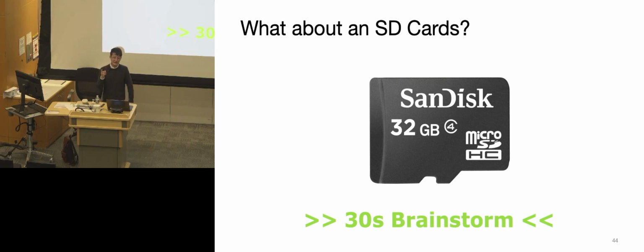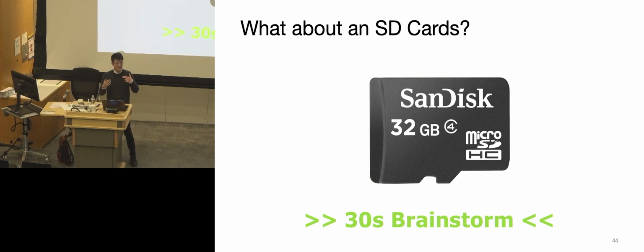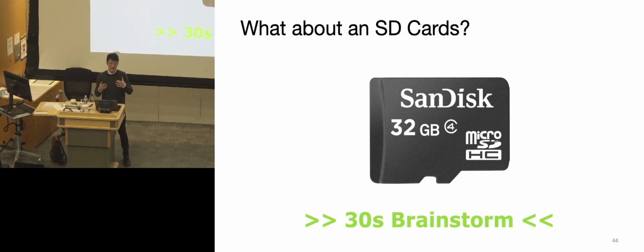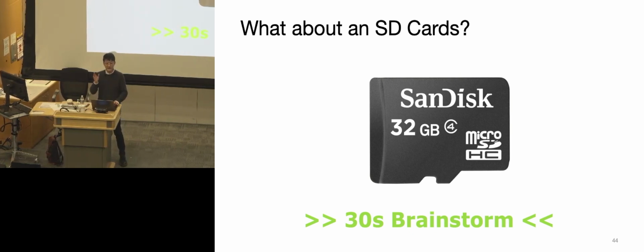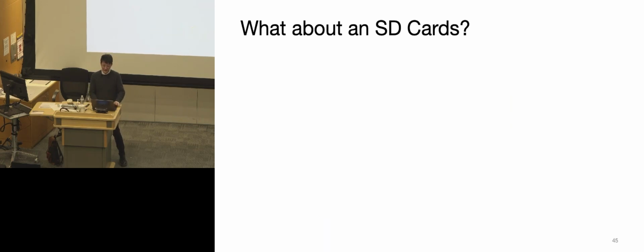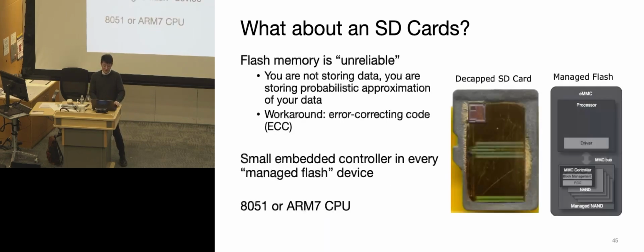I think that kind of answers the previous question, about just storing compared to the books. Compared to the books, these things can do input and output, in this case the SD card. So chances are there is probably some kind of control system on the chip, right? So in fact they are indeed embedded systems, and the reason for that is the communication protocol. They actually have a dedicated MCU, a microcontroller, inside each SD card nowadays.